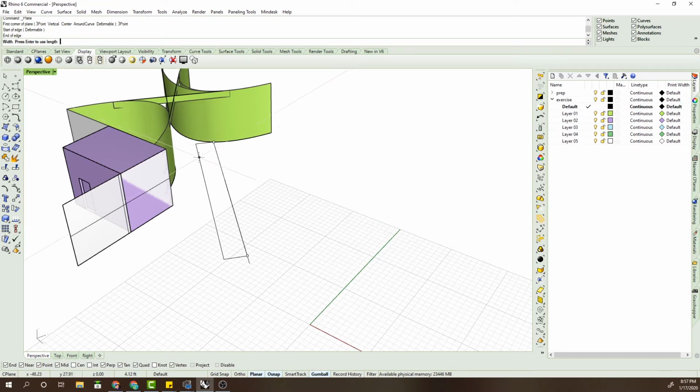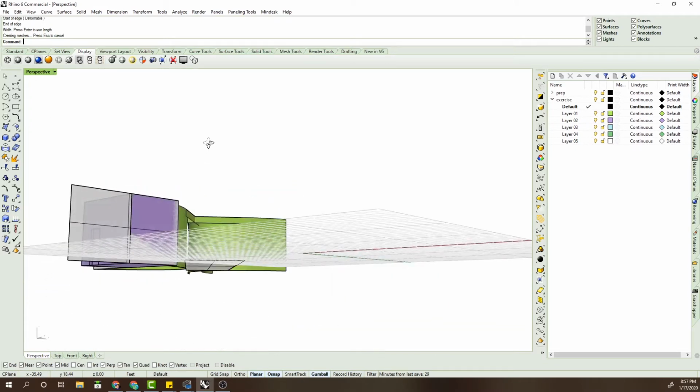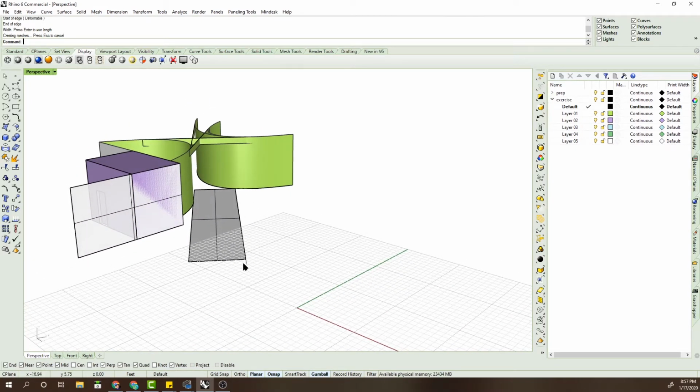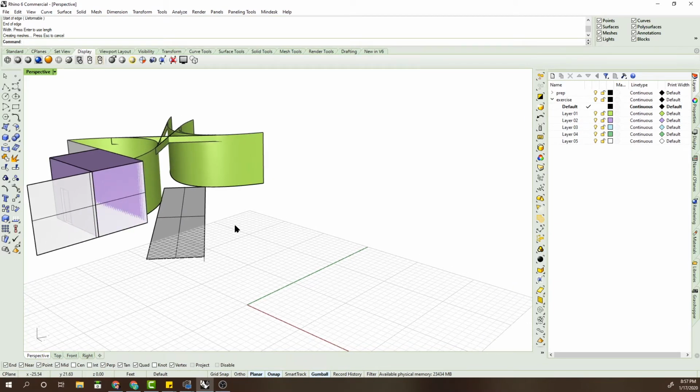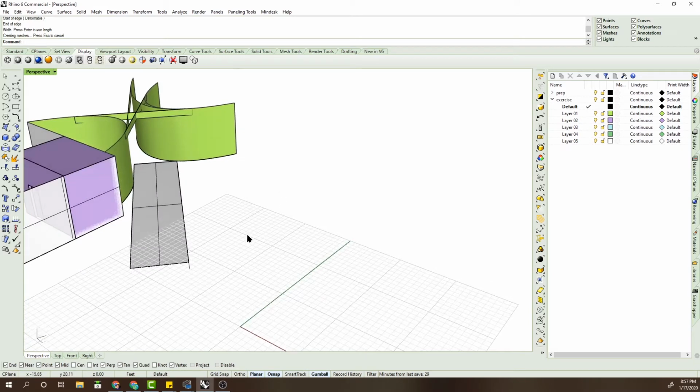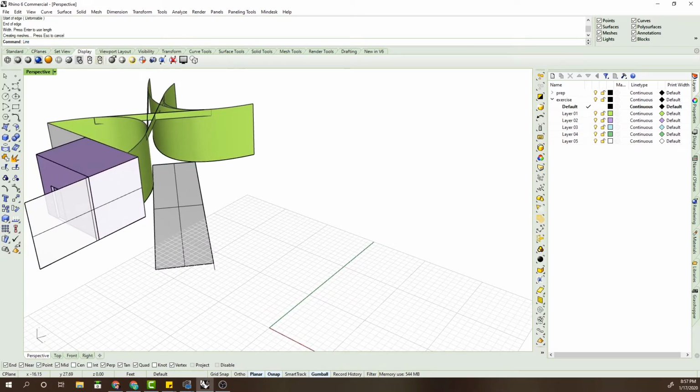And then as I'm going this direction, I want it to be perpendicular, so I'll hit tab again to lock that in, or not, and then just snap out. So now you can see I've got a perfectly flat surface that is perpendicular to this line here. So this is a really good way to get custom directions based on other geometry in your model. Okay, you can also do that with any modeling tools you do. So, like your lines here.